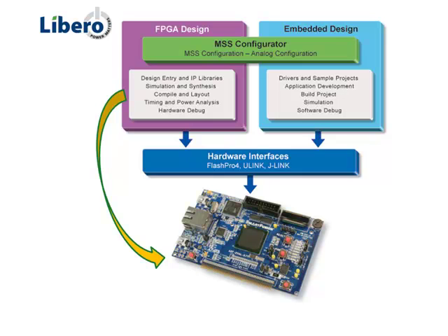It will show you how to create a SmartFusion project and configure several MSS (microcontroller subsystem) peripherals, including the fabric interface peripheral that allows you to connect the MSS to other logic blocks on the SmartDesign canvas. The logic blocks can be cores from the Libero IDE catalog or user-created HDL blocks that have been imported into the Libero IDE project.